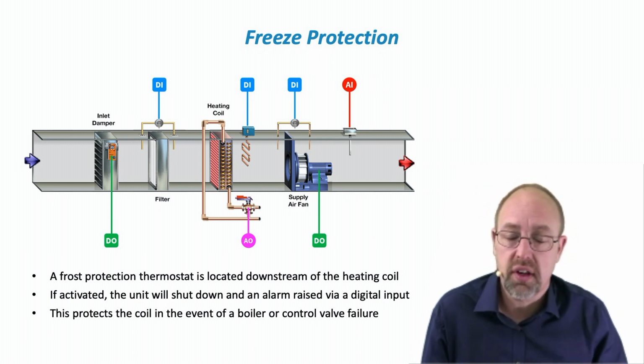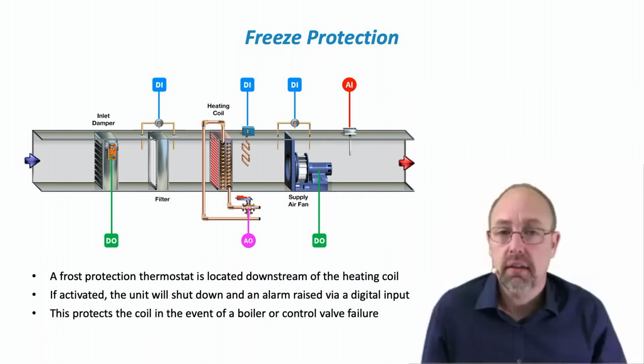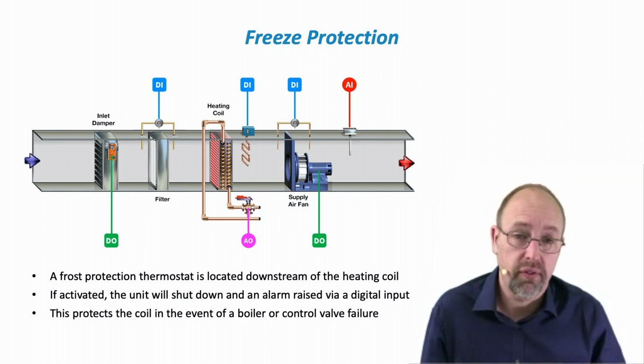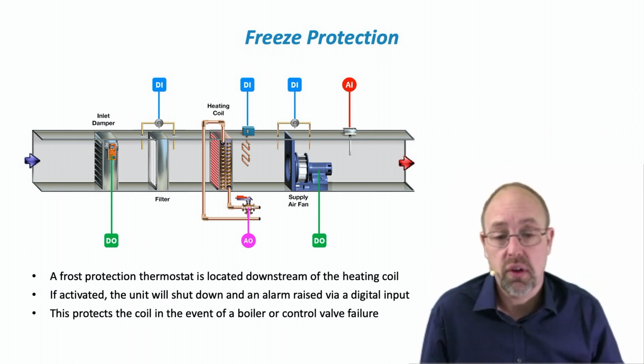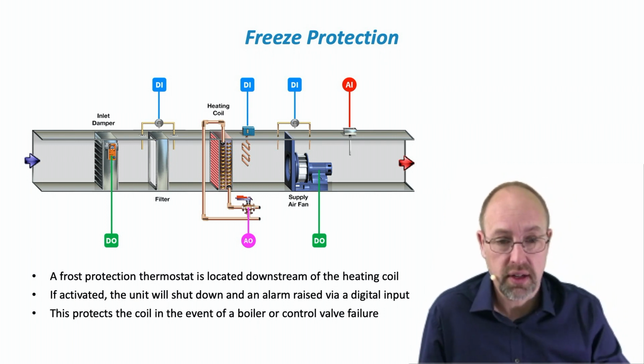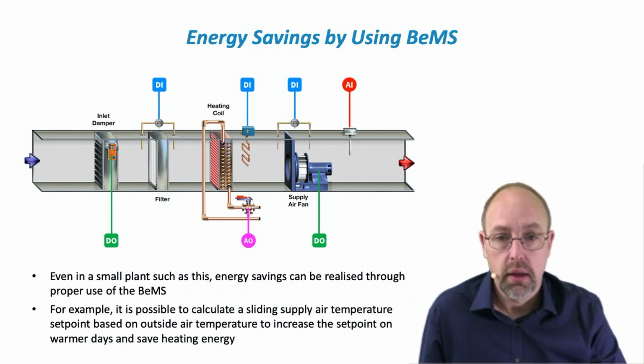But you want to know that that's happened. So you would take the status of that freeze protection thermostat and feed that into the BEMS so that someone would actually know about it.